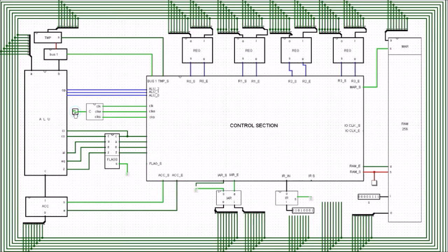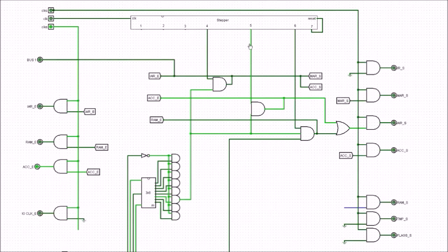So if we head on to get the next position, we go up to our clock, which is now enabled, and we can head back down in here and see we're on this position here. At position number 5, the accumulator has been enabled with the new value, and it's just sitting there, and whenever the clock set comes along it will get passed to the instruction address register.